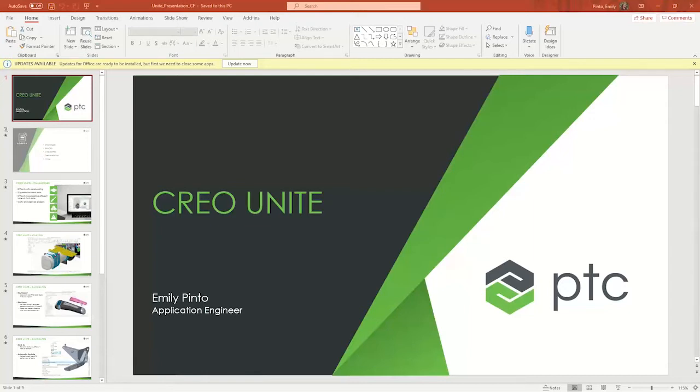This is a technology inside of Creo Parametric that's all about dealing with non-native data. It gives improved import of non-native data, CAD models. It also gives you the ability to open that data in its native format inside of Creo, and a save as capability to save models from many different CAD platforms that have been brought into Creo. You can save all of that as a non-native format, so you can save it as a SolidWorks or a CATIA or NX file. So you could send that to a vendor, supplier, or customer.